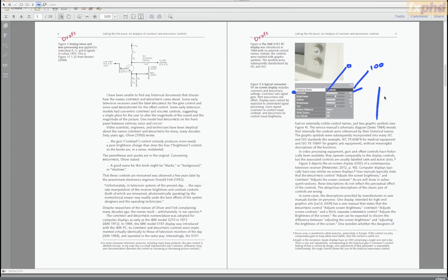So they don't tell you what the gain number is. And it's very, very unusual that you should have that brightness value depart from 0. Because in modern day displays, the circuits are very stable and the reflectance off the faceplate is very low. So typically you want the bias to be very close to 0.